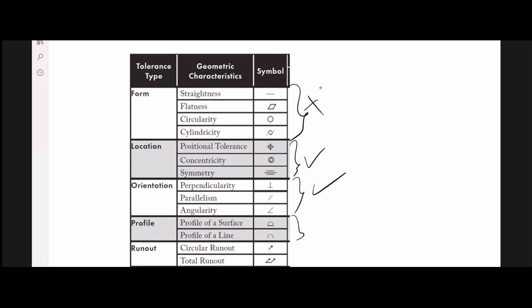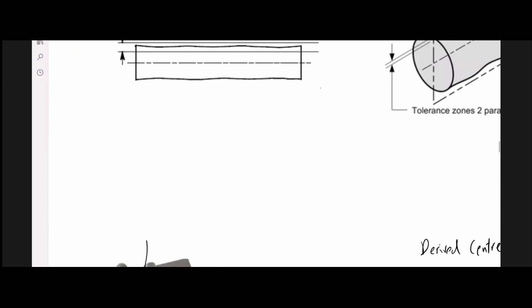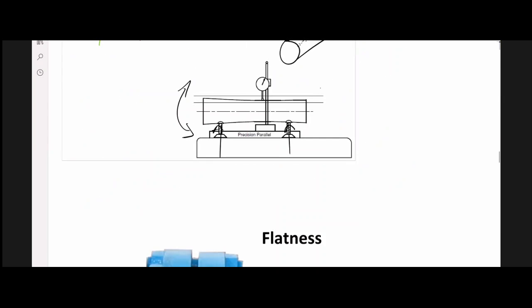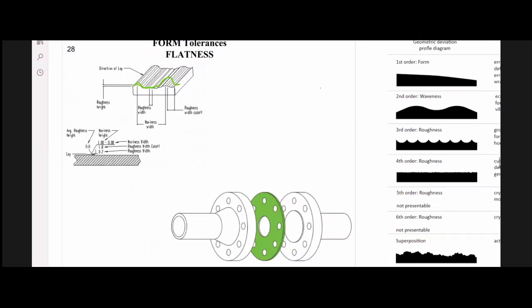These could, it's optional, depending on the use. And these also always have. I'll remind you again as we go through. But form tolerances cannot have a datum by definition, the way they're defined. As I said, I'll repeat some of these as we get there.